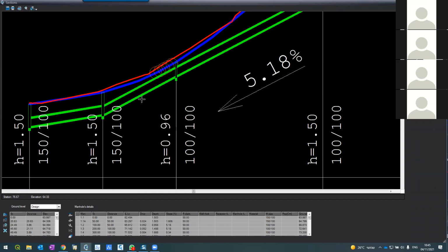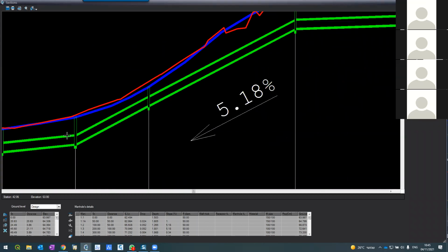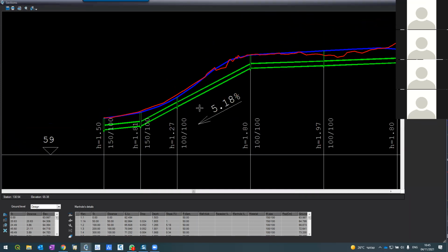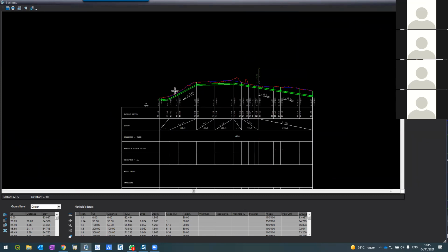I can fix it. How do I do it? You know what? Let's change the slope of this one. This is 1.6, make it 1%. Let's see. There it is. Okay, I changed it to 1%. So now this is 1% and everything changed accordingly. Other questions, please.